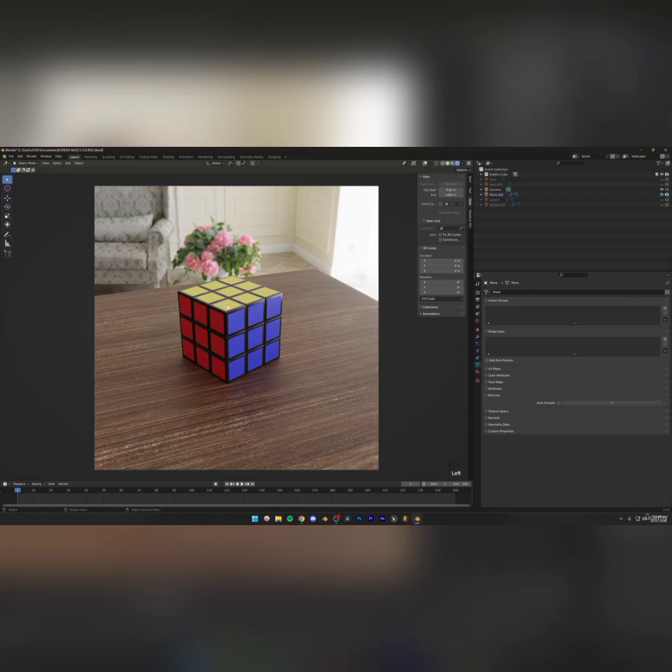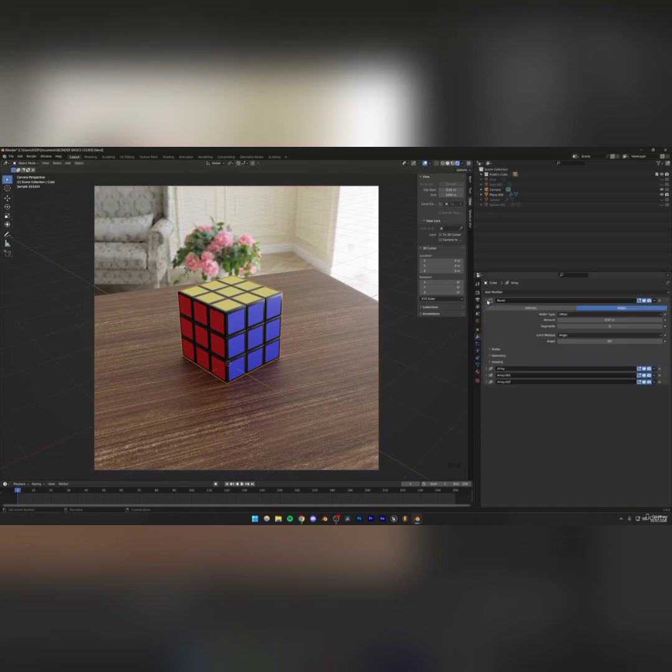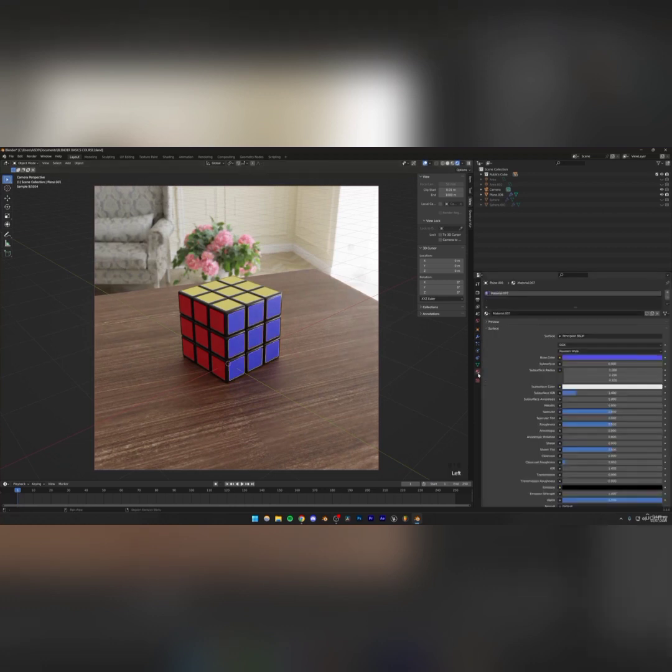One thing which I do want to do is increase the amount of beveling that we're doing. So I'm just going to select my cube. And this is the benefit of using modifiers, by the way. You can just modify the amount of beveling or anything else you do with modifiers, and it's very convenient. I think 0.15 is a lot better. Yeah, that's better.